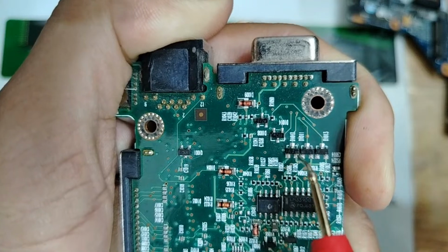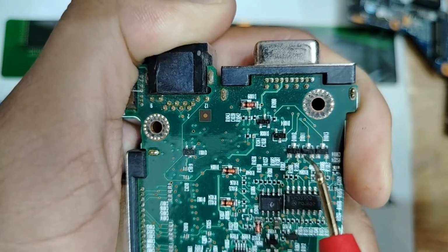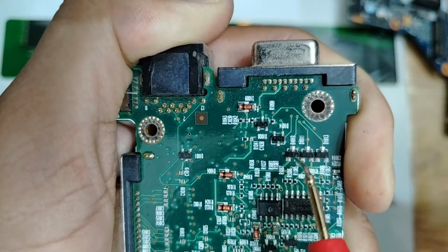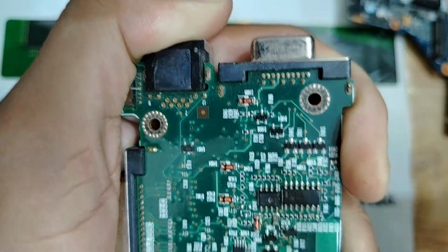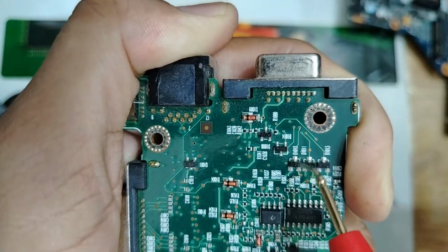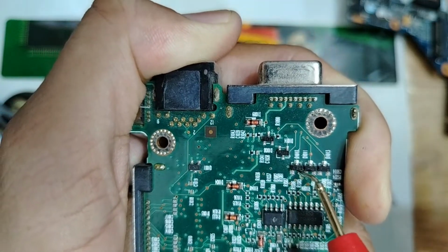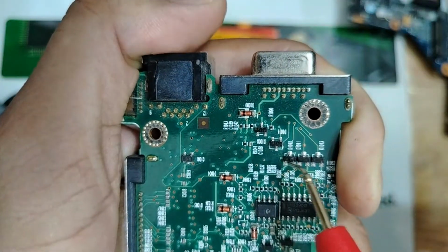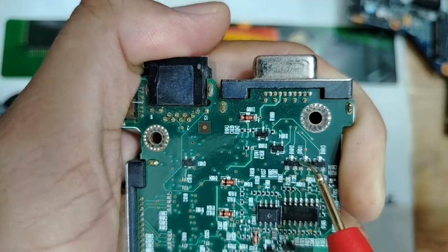It's different from the MOSFET. Please pay attention. Even in terms of testing, it's different from the MOSFET. In testing, we find two readings between this pin and this pin, and also a second reading between this pin and this pin. But for the MOSFET, we find just one reading.